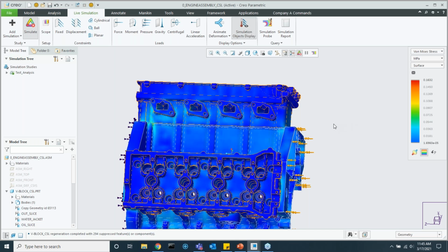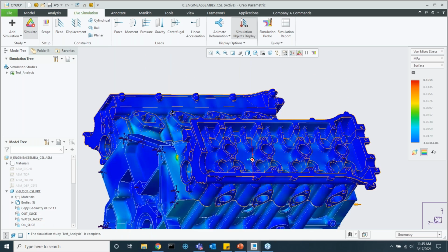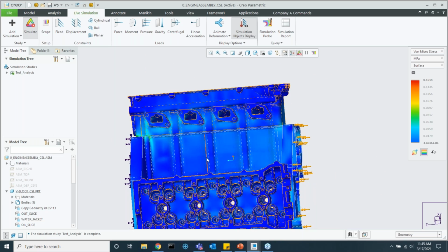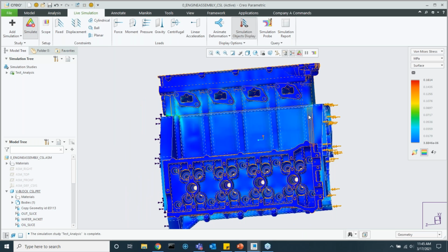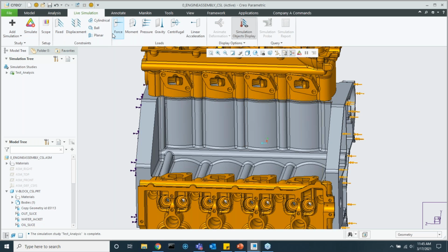Whereas if I wanted to see this in Creo Simulate, Creo ANSYS Simulation, or any other traditional FEA tool that you might export this out to, that's going to take another couple hours to see your results. And the end case might just be, hey, my design choice actually was bad and it increased the max stress in my part. And so then you just lost 3 hours. Whereas with this tool, if we saw the max stress went down, we can confidently say that this change did lower my overall stress. Now, by how much, that exact value might be a little bit more erroneous in this tool, but we are at least able to understand trends. So that's where this tool really does shine.